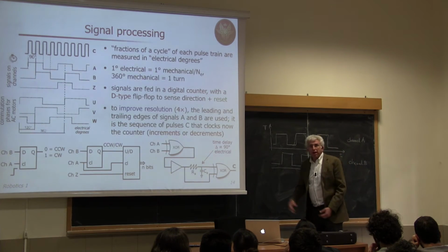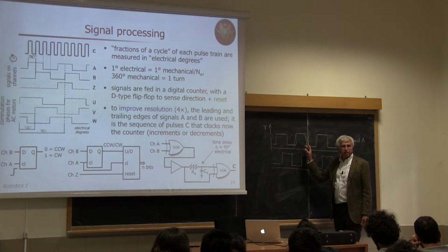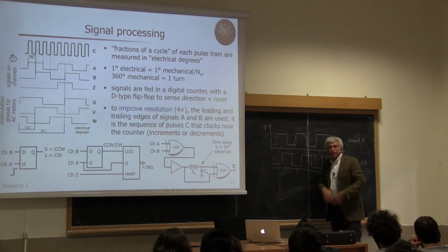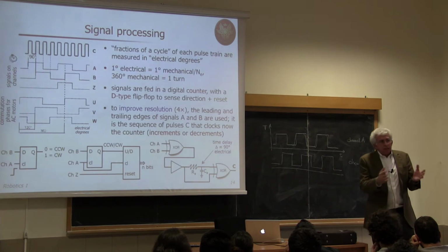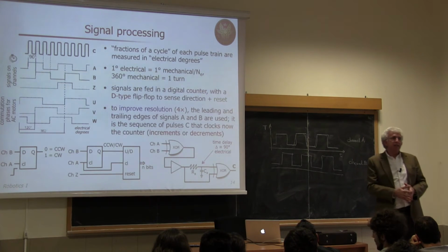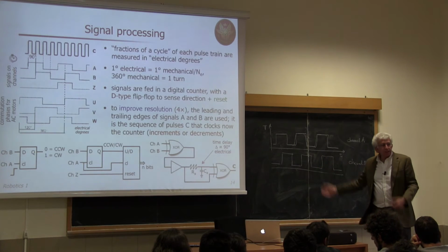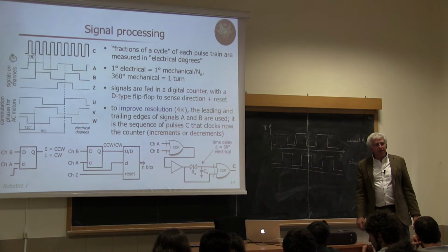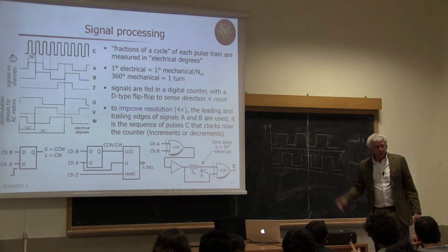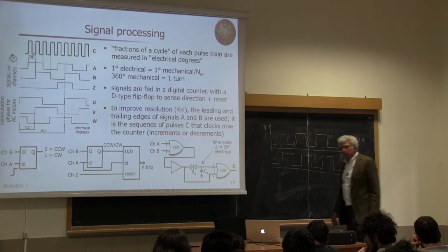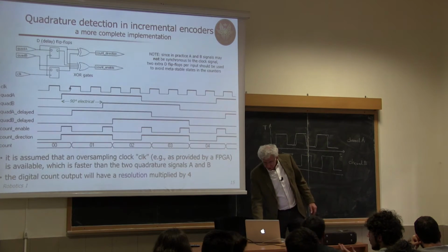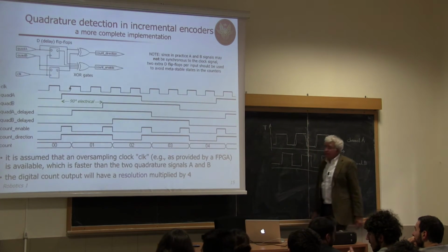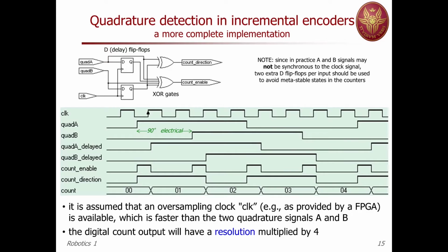So there is some blurring of things, and if you then multiply things, this blurring at some point will be such that you have more noise than signal, and there's no sense of dividing further the timing frame with this technique. Okay? So 4 is the standard solution. Here, this type of operation is also called quadrature detection.